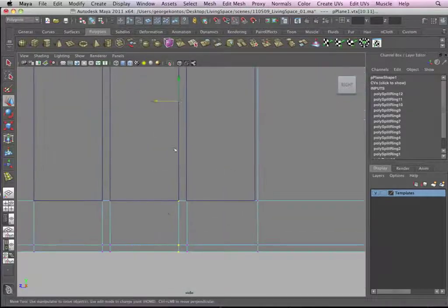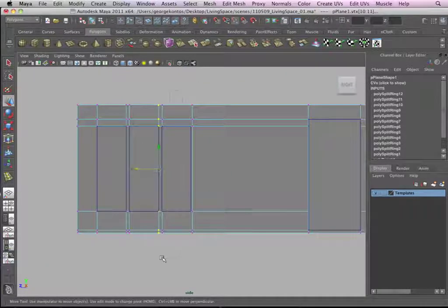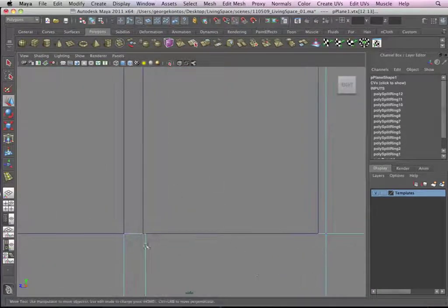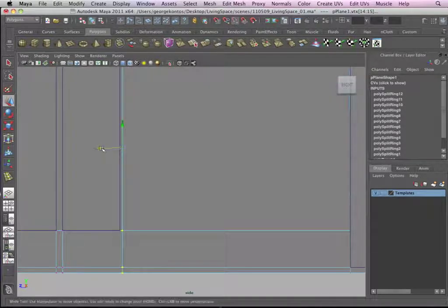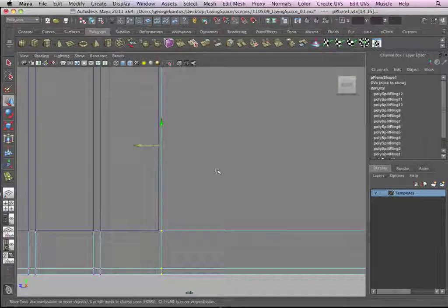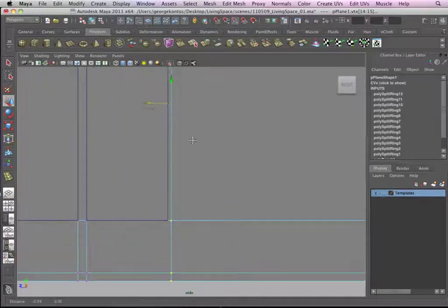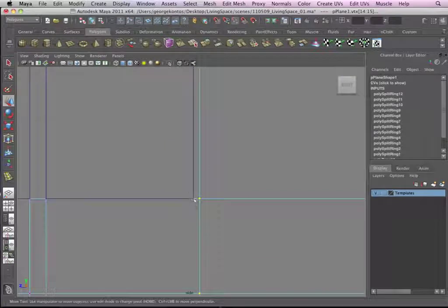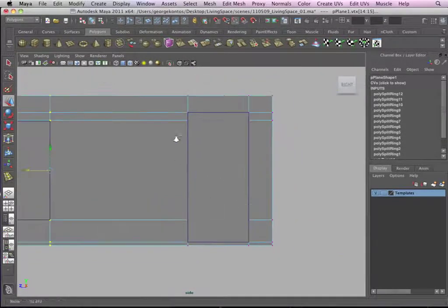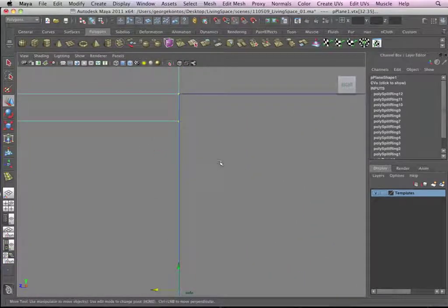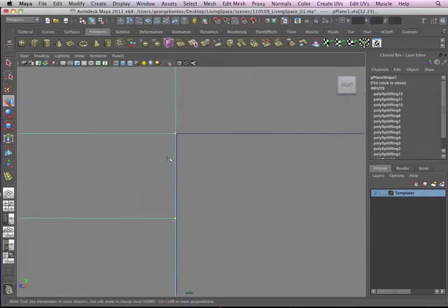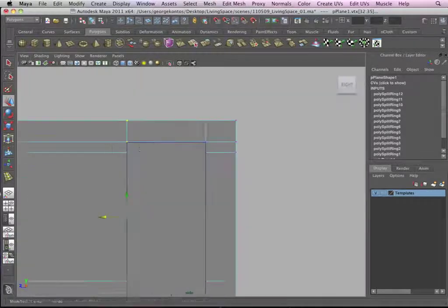Some of them are very close, so it's really already there. So select the points, make sure this is yellow, the axis that we need to move the vertices, and then go to the point that you want to snap them to and click there. Sometimes only clicking won't work. Holding down the middle mouse button and drawing around it will work. It's a little bit of a weird operation.